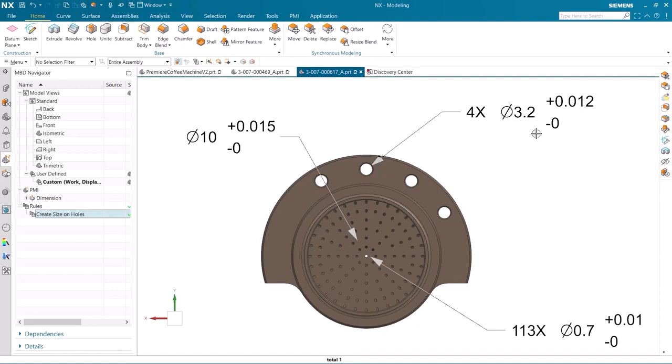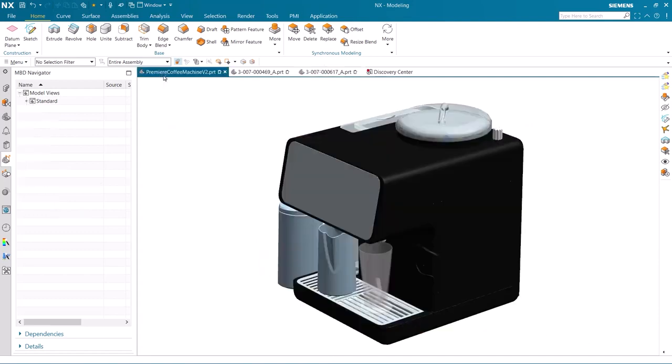Let's recap what you have seen. You saw me open an assembly and use one of the over 100 out-of-the-box MBD rules. We quickly added a part table in the 3D model to the product definition with the associative part table itself, consisting of the components and selected attributes, as well as the labeling tied to each component. You then saw me toggle on the emphasis view option to more easily locate specified components of the part list in the 3D assembly. The components were selected out of the part table and emphasized in the graphical window.